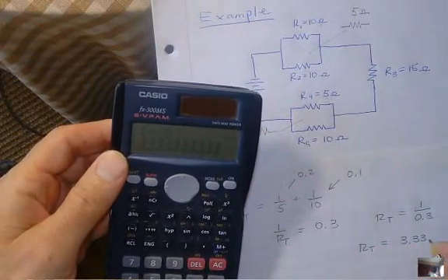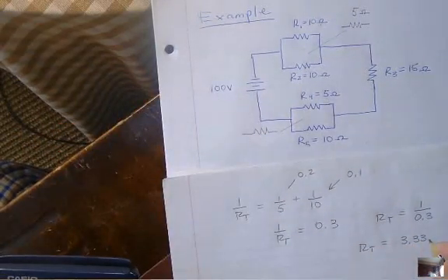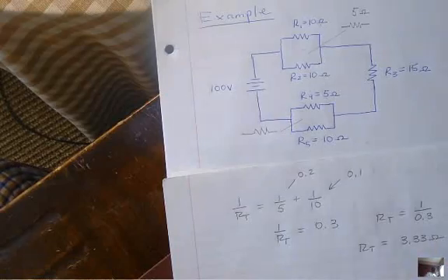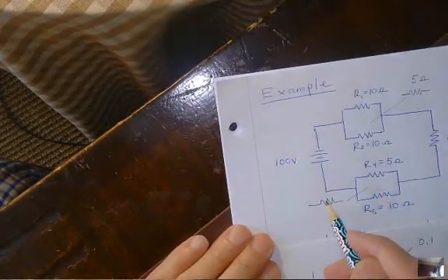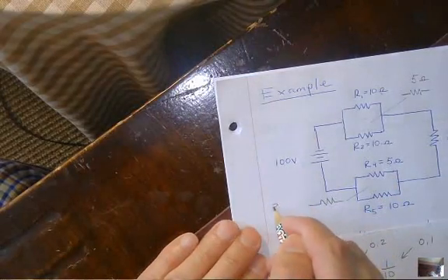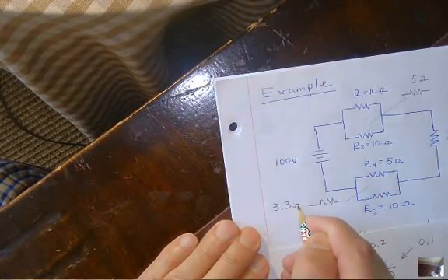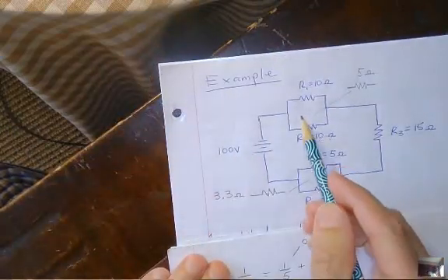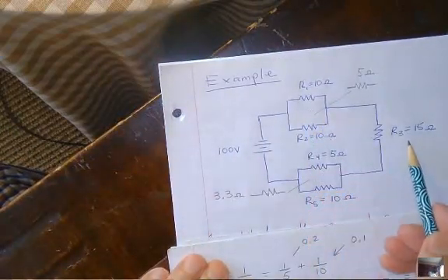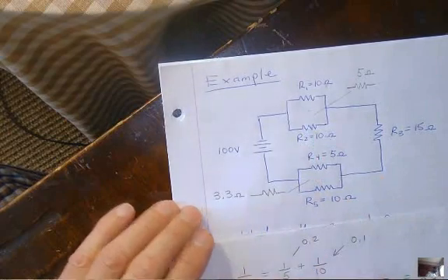So what did I tell you? It's always less than the lower one. In this case, it's significantly less. Okay? All right, so going through this way where I have a choice would be equivalent to going through one that was 3.3 ohms. Okay, now I have it easy. I have a 5 here, a 15 here, and a 3.3 here.